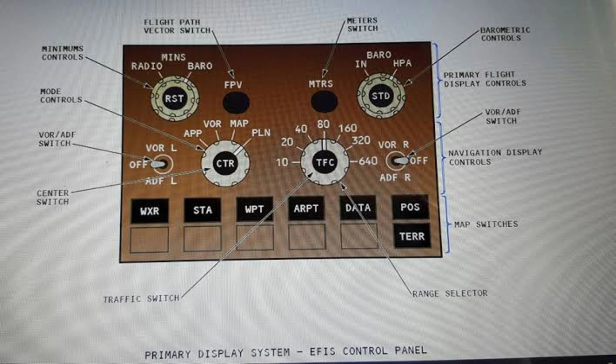And the right hand side is the co-pilot side. So the right hand side is the terrain button, which is used by the co-pilot if the co-pilot is acting as a pilot monitoring or the pilot not flying. So he or she will be using the terrain button. Though it's not a memory item, the pilot is just supposed to see the switch and use the data accordingly, whatever information is required to be seen.